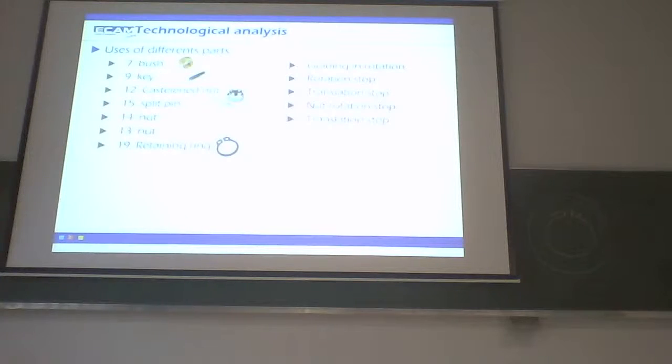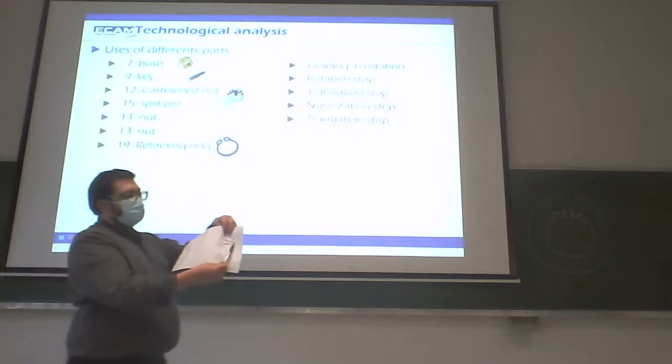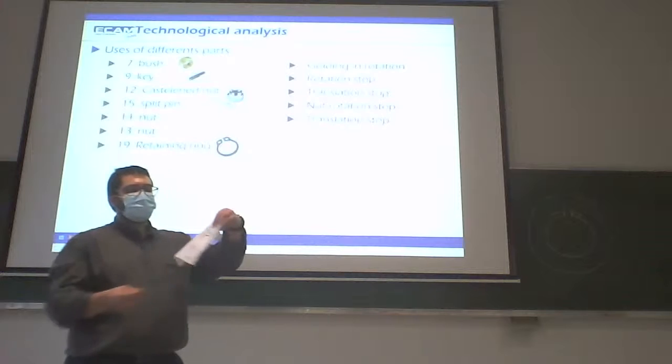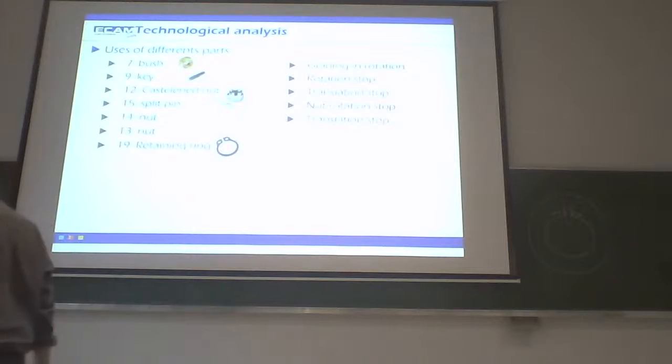14 is here, in contact with the pulley 10. Okay, so it's also a translation stop. And the second nut, okay, it's a lock nut. You have an assembly with 2 nuts. So the second nut is a nut rotation stop.